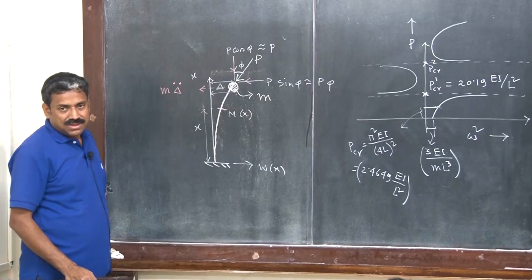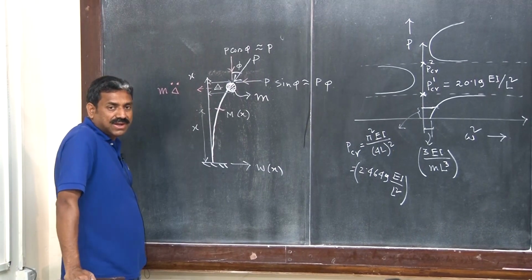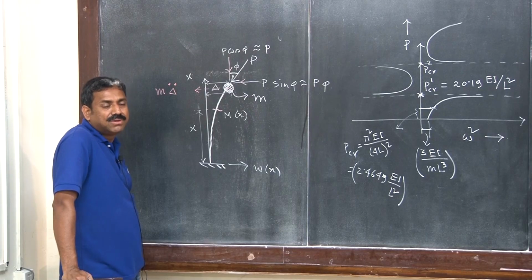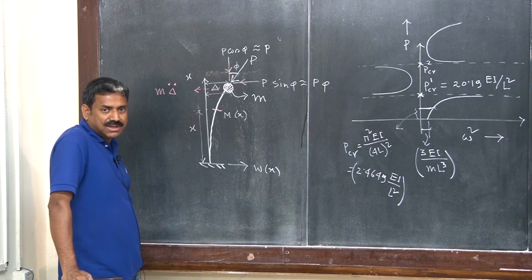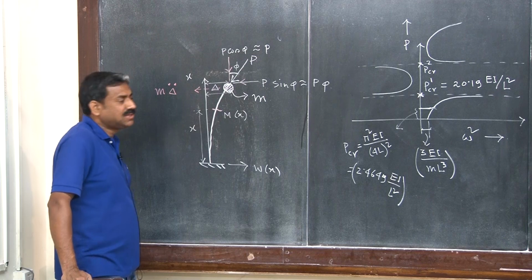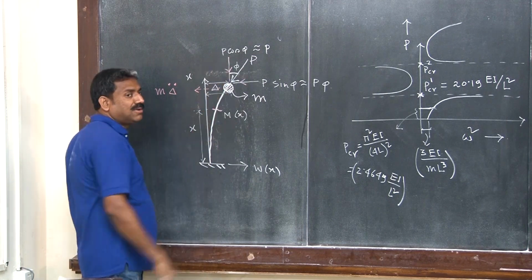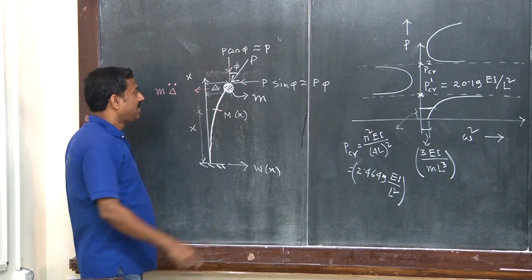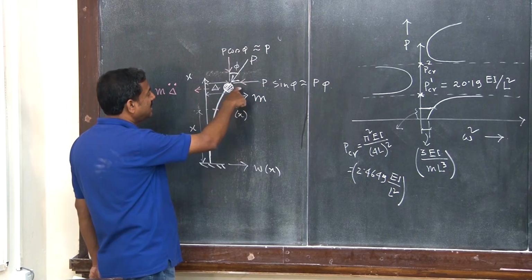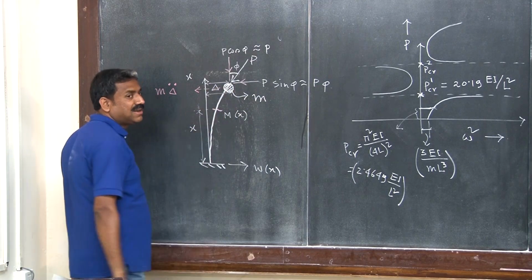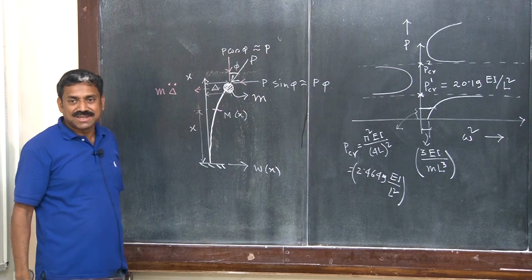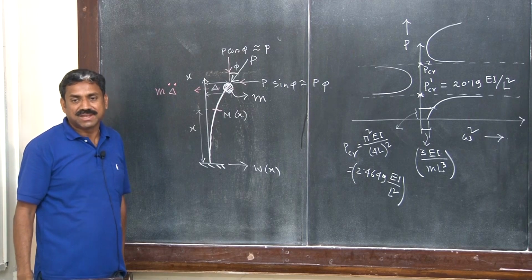If the force is a vector and the displacement is a vector, you take the dot product. If it is 90 degrees, then cos 90 degrees is 0. So when it is a vertically applied load, no work is done. But when it is horizontal, this component is acting on this lateral deflection, so that basically is doing work, and that work is dissipating.